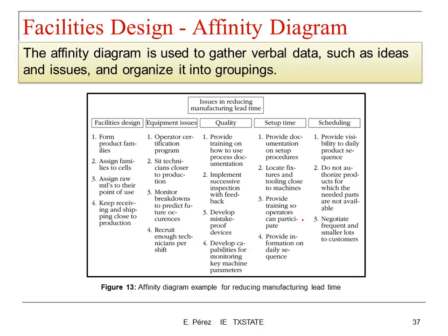If you are not familiar, a cell is a concept used in cellular manufacturing, in which, if you have products that are similar, you can produce them using the same production line. But this production is not formed in a line, it's formed in the form of a cell. Most of the time it's in a circular way. So you can use the same equipment, same materials to produce different types of products that are similar.